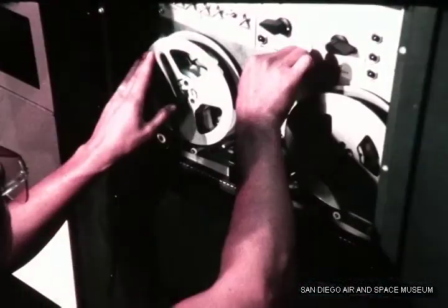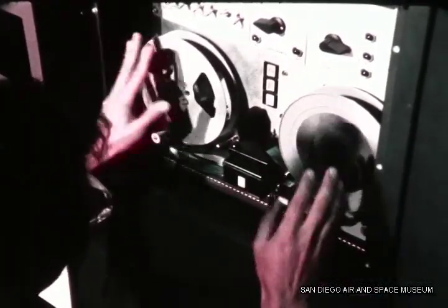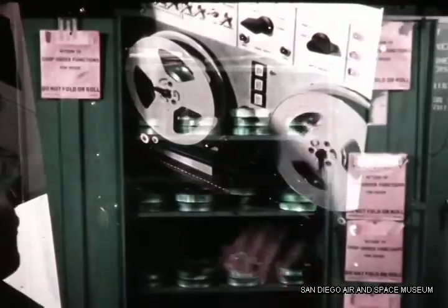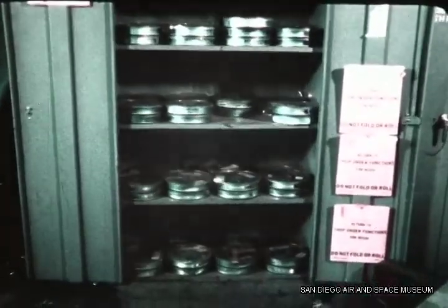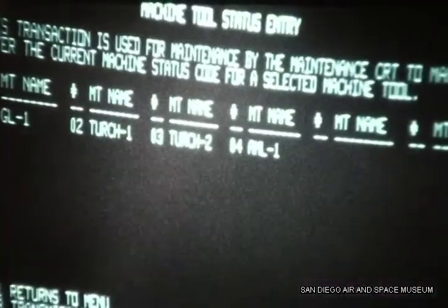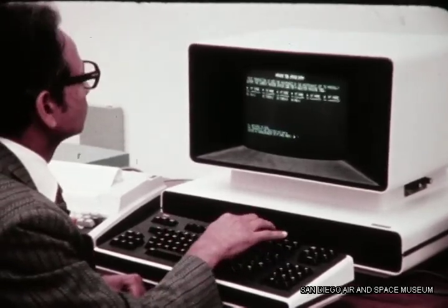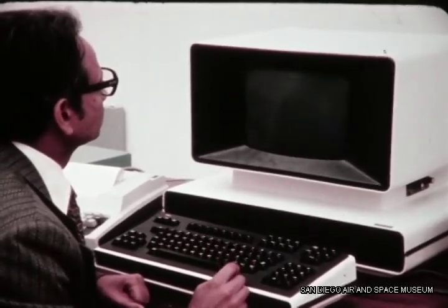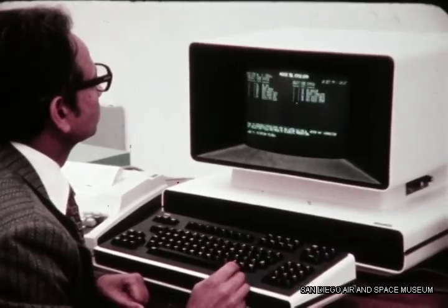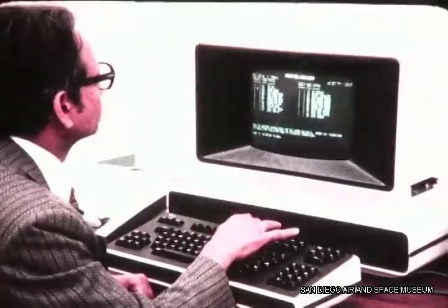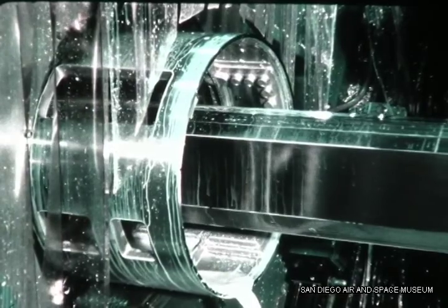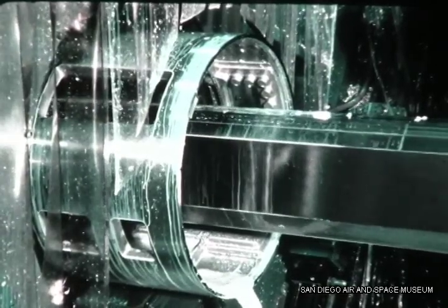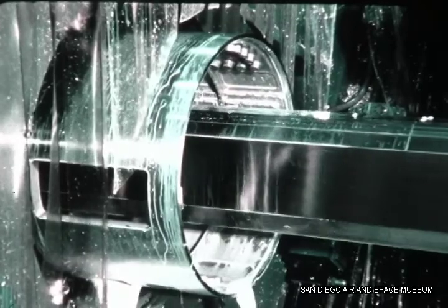Benefits of DNC include the elimination of tapes, which must be cataloged, stored, handled, may be damaged, and are expensive to make and replace. The computers provide a real-time status monitoring system to monitor tools, parts, equipment, and labor. This information is readily accessed by all who are affected and concerned with operation and support of the numerical control machining functions. A much improved utilization of equipment under DNC makes it feasible to keep the machine tools operating a high percentage of the time.